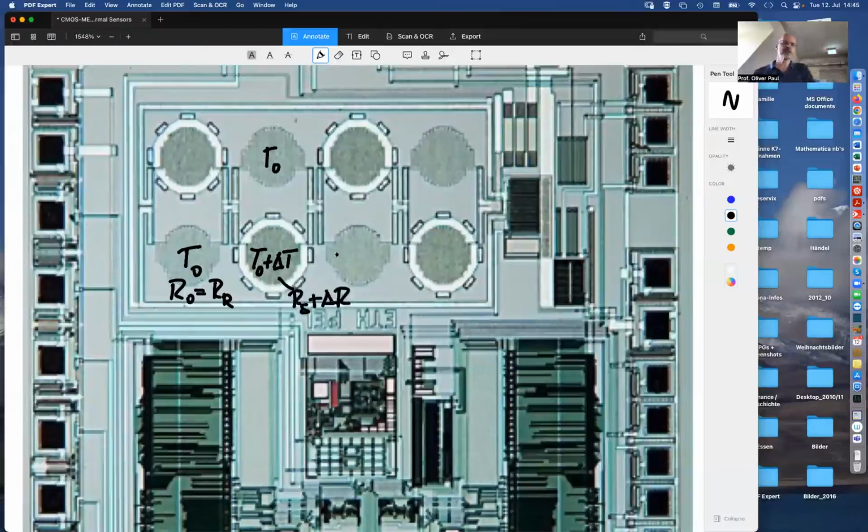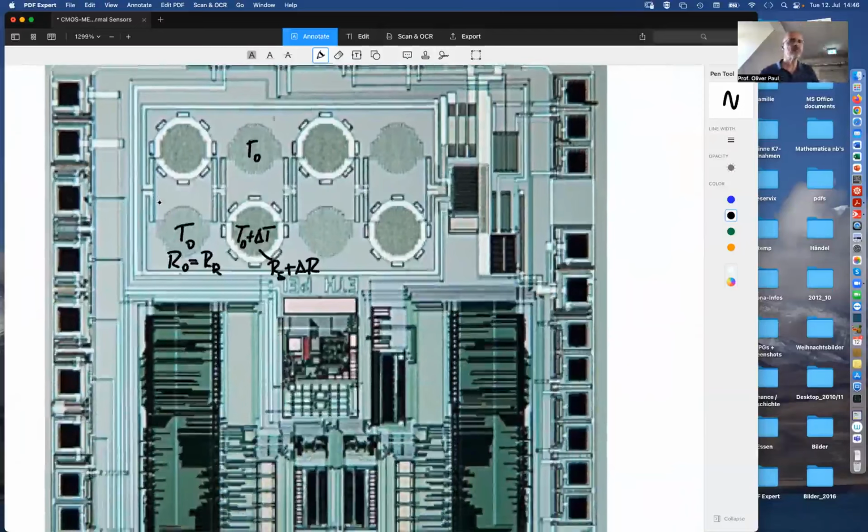So this is how these resistors were implemented, and what you also see is the beautiful shining structure of this disc, which shows in this optical micrograph that the aluminum is still visible. Aluminum 1 was not yet sacrificially removed. That was a chip photograph before micromachining. That's also what it tells you. And then I see more.